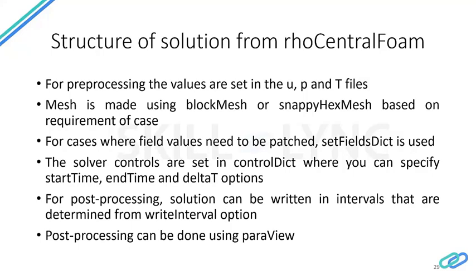This can be done in CFD using patching. At that particular time step after fuel is injected, you can define a particular temperature value at the base of your piston cylinder configuration, and that will simulate your spark. This can be done in OpenFOAM in the setFieldsDict file.